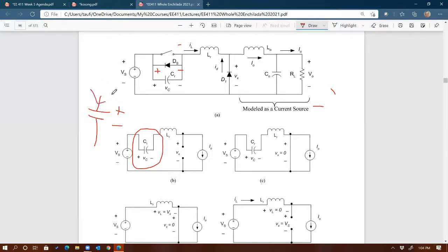All right, so the current flows into the cap, therefore we are charging that capacitor, right? How are we charging that capacitor? Linearly. How do I know it's linear? Can anybody answer that? The current's constant because it's in series with the inductor and the current source. That's correct. Why is it that when the current through the cap is constant, can you show me the mathematical equation that proves that's a constant, linear slope on the voltage? I equals C dV/dt. Very good. So I know that for a capacitor, IC is equal to C dVC/dt.